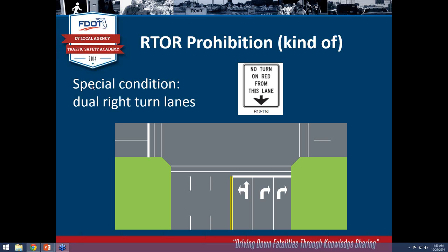They did a lot of studies, and studies have shown that the corridors typically are safer staying in green, yellow, red operation 24 hours a day, just because you don't have that late night period where you have some impaired drivers out there driving very fast. So you have all the things working against you when you flash them at night. And nowadays we have LED indications, so you're not burning too much power anyhow. It's just a lot of safety concerns at those intersections when you are flashing them at night, and a lot of that does go away when you go into full green, yellow, red operation.